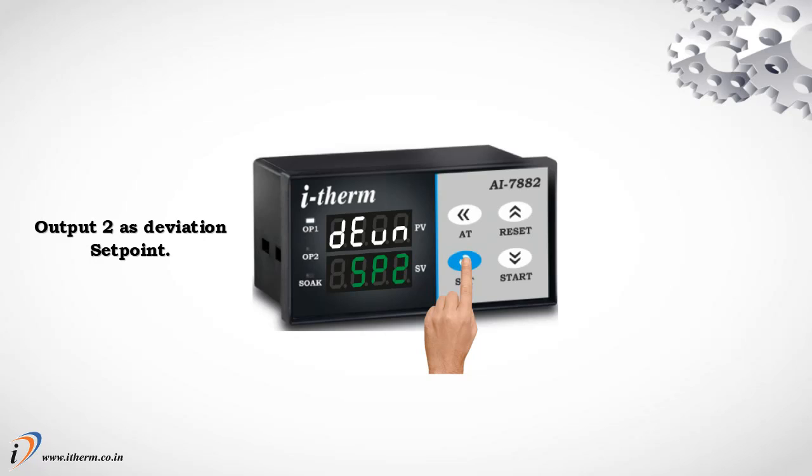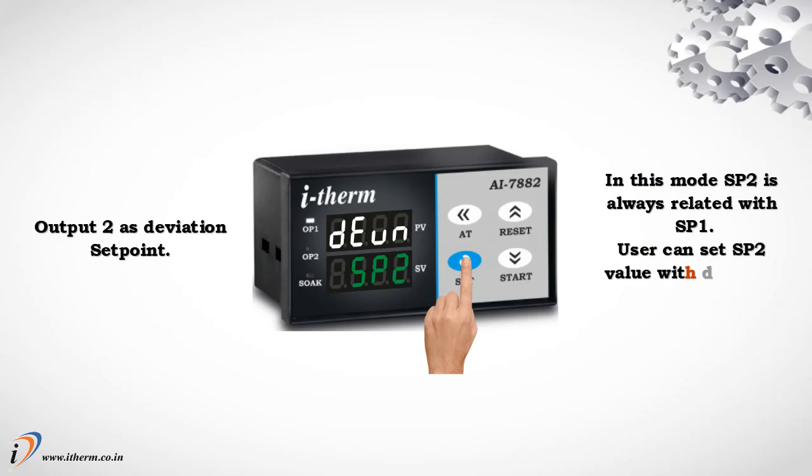Output 2 as deviation setpoint. In this mode, setpoint 2 is always related to setpoint 1. The user can set the setpoint 2 value with a deviation of plus or minus 99 degrees Celsius with respect to setpoint 1.